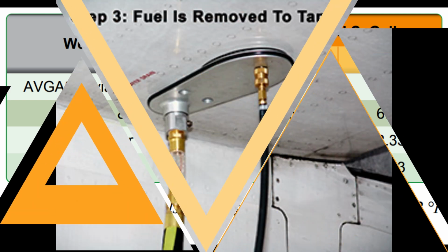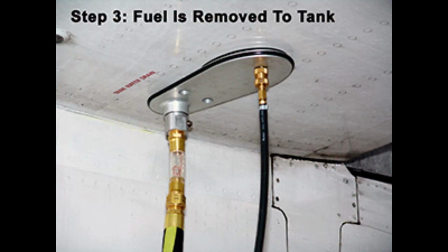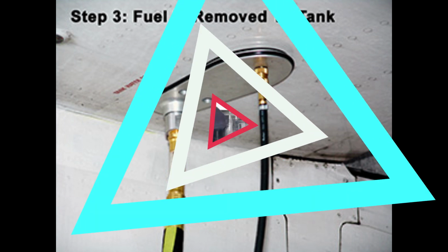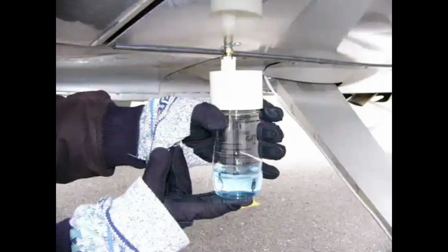Draining the fuel. Drain fuel from the tanks in the manner specified by the aircraft manufacturer. If there are no specific instructions, drain the fuel until the fuel quantity gauge reads empty when the aircraft is in level flight attitude. Any fuel remaining in the system is considered residual or unusable fuel and is part of the aircraft empty weight. The amount of residual fuel and its arm are normally found in Note 1 in the section of the Type Certificate Data Sheets, TCDS, Data pertaining to all models. For additional fuel capacity information, see Chapter 2, Weight and Balance Theory.